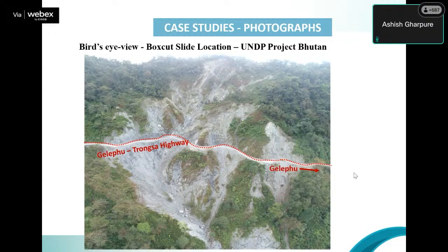But actually, we are going steeper and steeper in that way, and more susceptible to fall also. Again, the decision may differ from location to location, but in a generic way, I would avoid that and see the protection work first rather than bending the road and circling around.